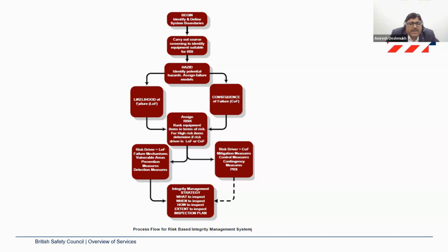However, if I'm trying to focus on the outcomes or the consequences, the area that I'm really looking at is the mitigation side. I look at the active protection layers, your pressure relief valves, the PSV system that you have, or if you are looking at the blast walls or the blast zones, that is the passive protection layer, and the last layer is the emergency protection layer.